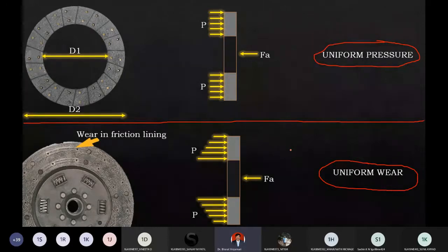Okay. Now what does this mean? First of all, see this. Pressure is when I apply the force from our side. The pressure is from the flywheel. The pressure is applied from the flywheel on the other side of the friction plate. This is the thickness H. Now, how this pressure is applied and why I call this uniform pressure is what we need to understand.